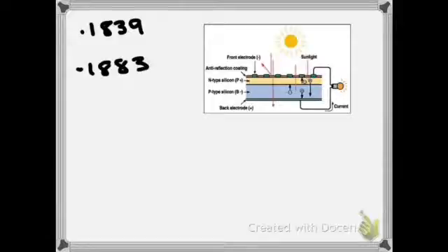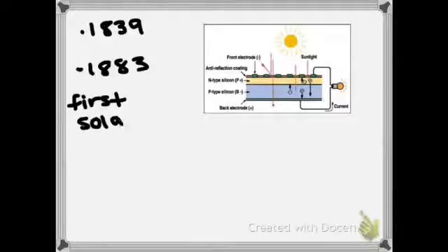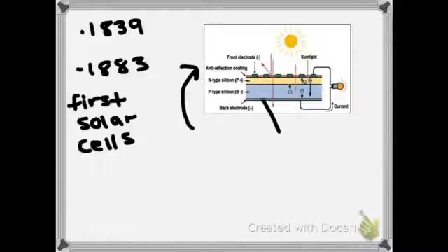In the picture, you can see that this effect is implemented in photovoltaic cells or solar cells, which convert light energy into electric energy. How do they work? In the picture, you can see that photovoltaic cells are made up of several layers, including an anti-reflective layer, metallic conductors, and silicon layers. The most important layers are the N and P layers, composed of two semiconductors, an N-type and P-type. An electric field is formed when these two layers join. Electrons move to the positive P side, and holes are created in the negative N side.